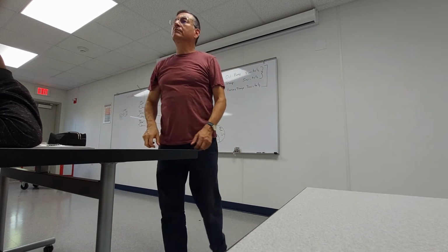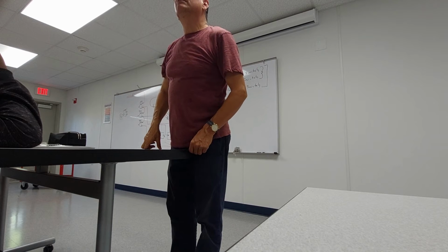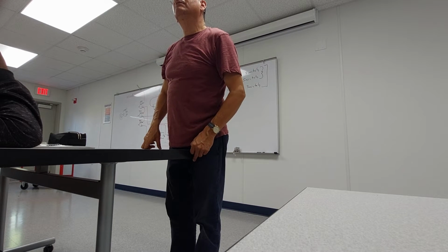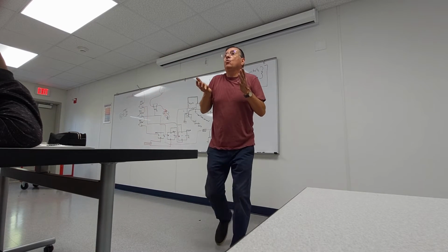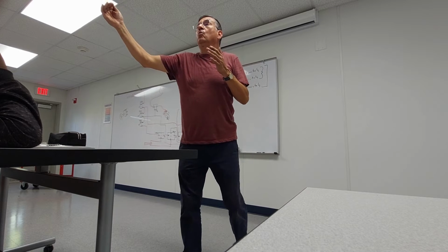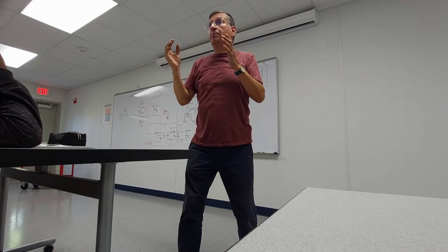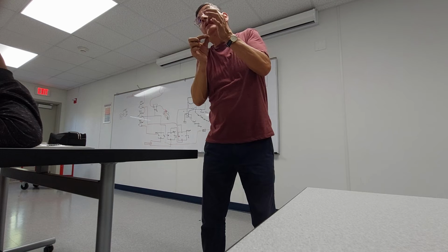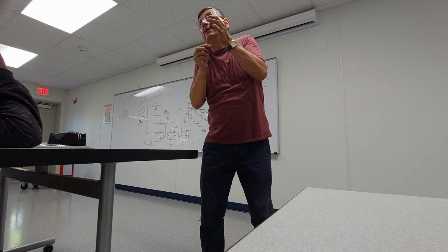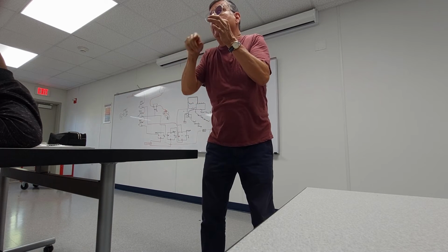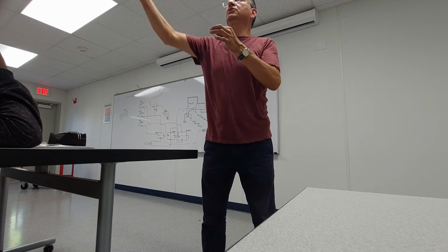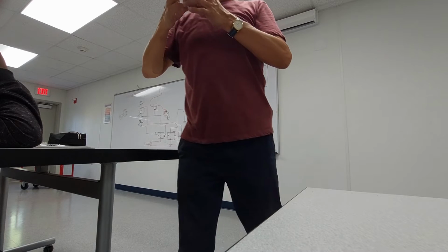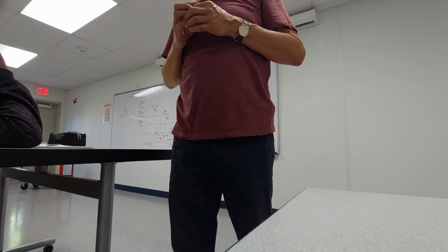The question is, you have a sensor, right? Why do we have a switch near this housing? Pay attention. I need to interrupt when the temperature passes the limit. How do I know if the temperature passes the limit? Because I have a switch with a sensing element at the bottom that senses the temperature of the coolant. When that temperature passes the limit, the contact opens and interrupts the current. It protects the motor.